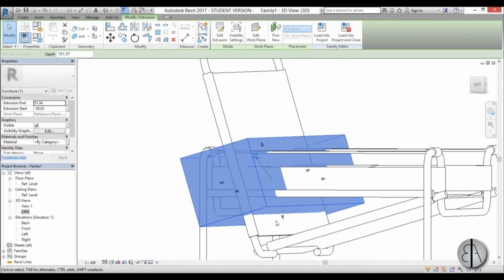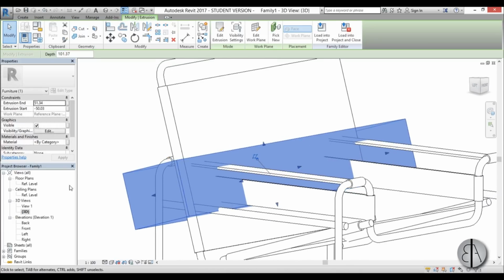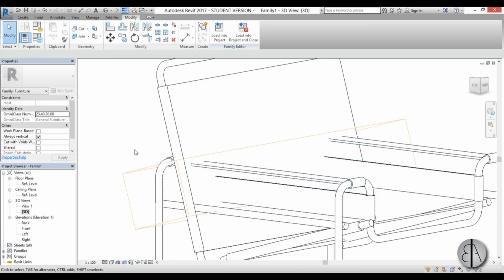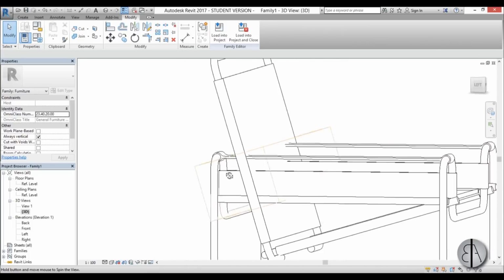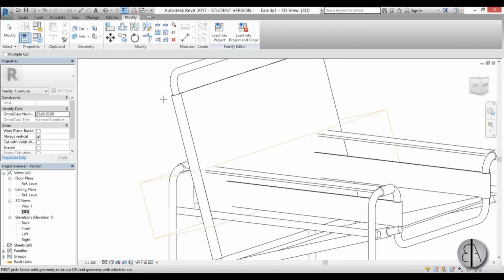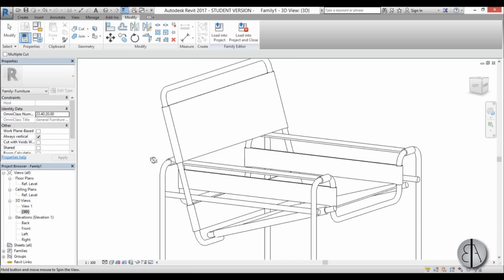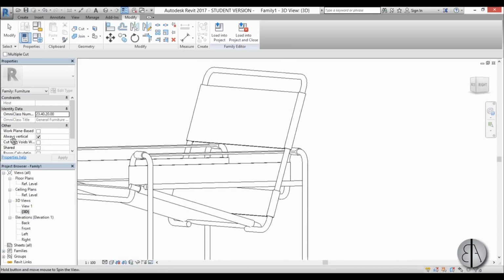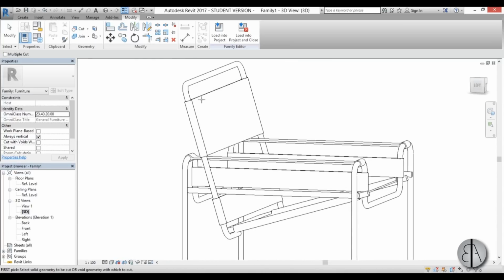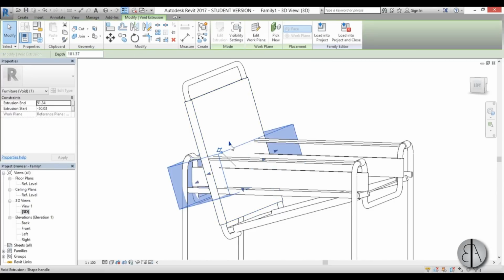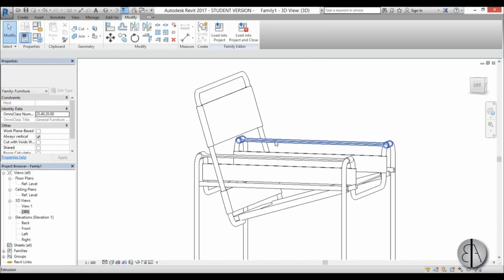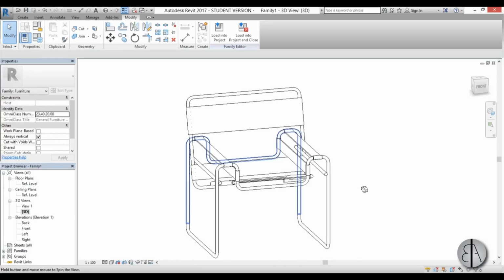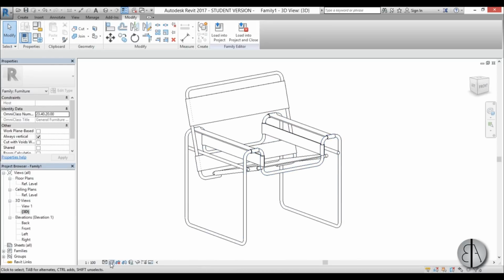Yeah, we can pull up this bottom part a little bit like so, and now we go here into the properties panel and we go from solid to void, and now it's a void and it isn't cutting anything, so now I can go into cut tool and choose what I want to cut. Okay, that looks nice. Maybe this strap is a bit too big, so I can just extend this. Yeah, that looks about right, and let's just add the materials.